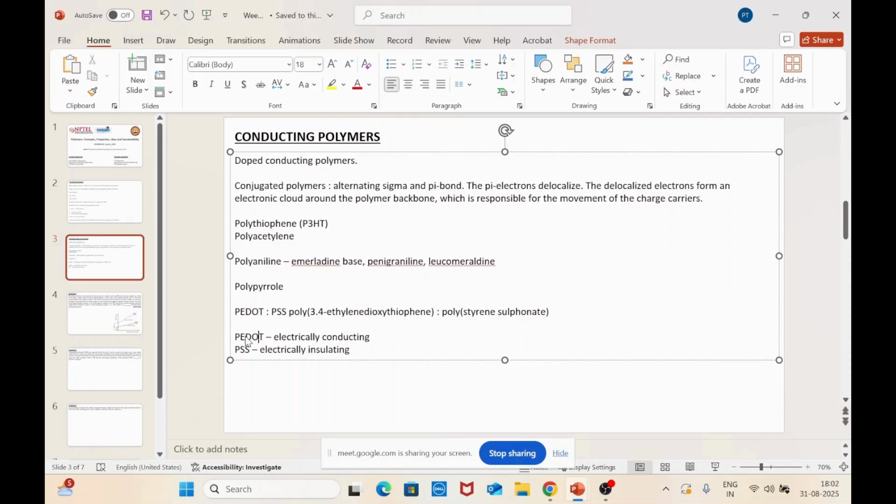So this is a kind of way to improve upon the charge transport in case of PEDOT:PSS. So doping is one way to improve the electrical conductivity of the polymers, but in case of PEDOT:PSS, apart from doping, we try to improve their electrical conductivity using different solvents. So as I said, depending upon the type of solvent and polymer interactions, the chain moves from coil to expanded coil state or to straightened chains, and this helps in the delocalization of the charges, thereby improving its electrical conductivity.